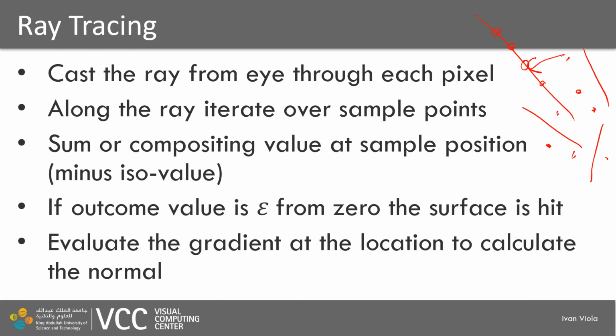We can perform various compositing techniques. It can be either the sum, but for some objects, we would like to maybe not perform the sum, but a union or an intersection or a difference perhaps. So this all can be realized, and we can already see that we can perform some constructive solid geometry operators on the implicit representation through performing the compositing not only as a summation, but other forms as well.